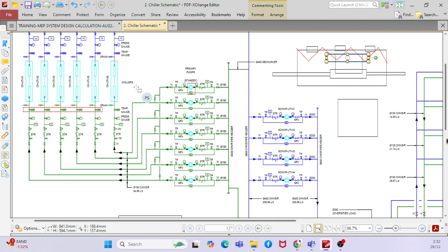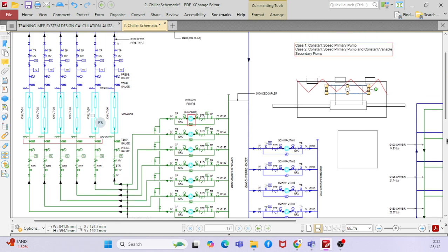Am I making sense? See what I'm saying. For example, you have the equation Q equal to m Cp delta T, right? The heat and the flow should be proper for the proper heat transfer. Based on that formula, delta T is proportional to the flow rate.